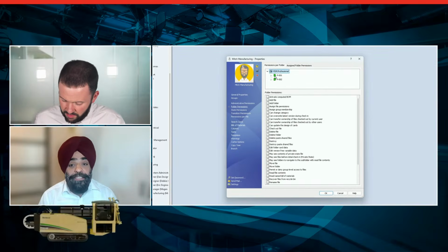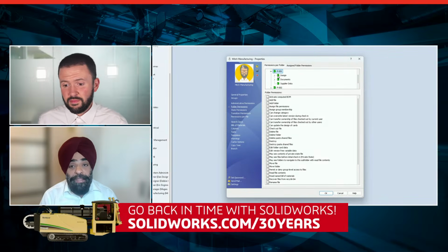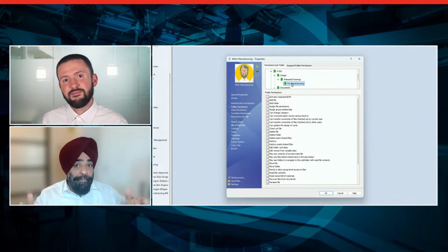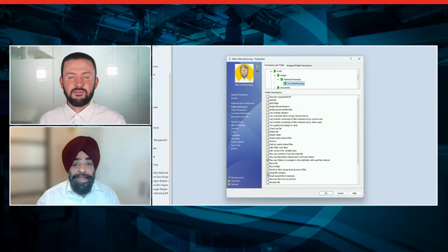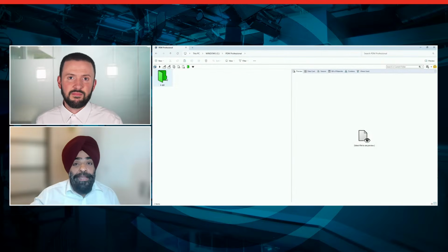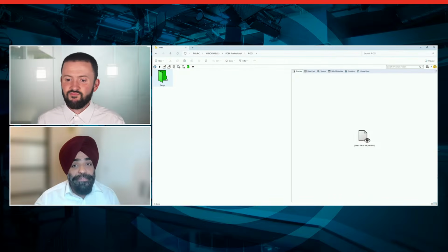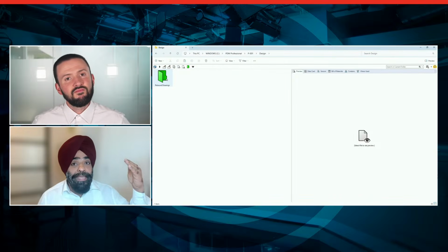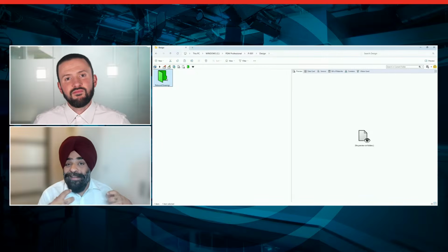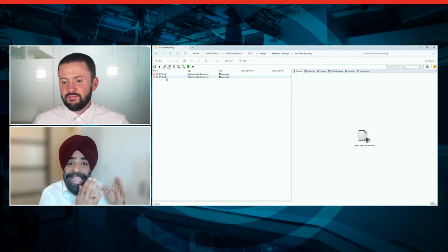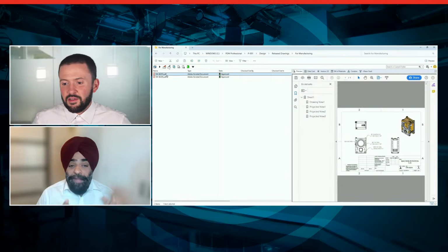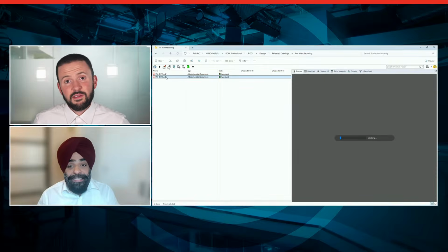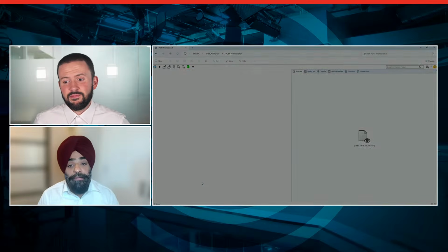So which is a big deal. And I believe if you are implementing PDM in a manufacturing workflow, wherein the manufacturing people only require access to a folder where you have your release drawing PDFs, they have the complete visual navigation, but they will not be able to see any other content of the parent folders. Yeah. So I would say it enables the targeted access without exposing the parent folder content.